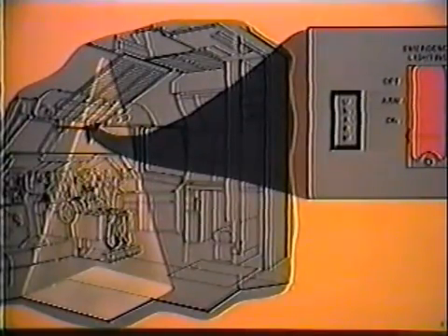Emergency lighting. The emergency lighting panel is located on the eyebrow panel and consists of a 3-position guarded switch and an unarmed light. In the arm position, the system is armed to activate all cabin and flight station emergency lights with the loss of DC essential power.